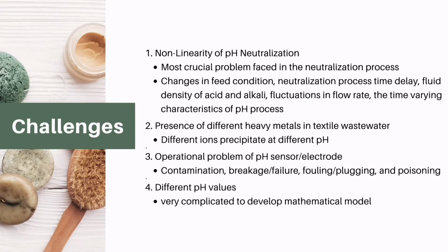Based on our research, we found out that there are a few challenging concerns for process control for pH neutralization of textile wastewater. These challenges need to be identified and minimized to improve the control system. The first challenge is the non-linearity of pH neutralization. Nonlinearity is deemed as the most crucial problem faced in the neutralization process. Some of the causes are the changes in feed condition, neutralization process time delay, fluid density of acid and alkali, fluctuation in flow rate, the time-varying characteristics of pH process, and etc. In addition, neutralization process will often be subjected to immeasurable and unpredictable disturbances.